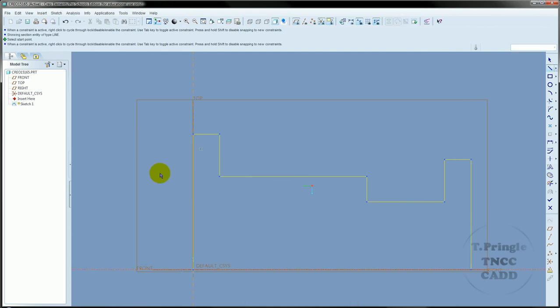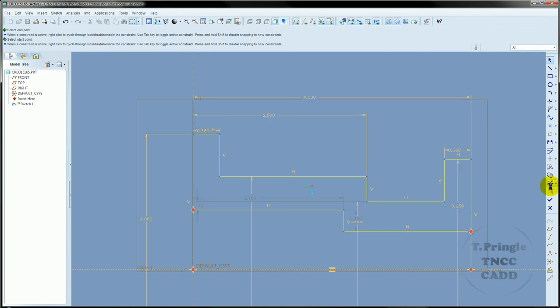What I'm going to do now is draw 2 lines, just come over this way, down, and then out to the end here. And now I'm going to delete segments, and I'm going to delete this segment and this segment. Now what you'll notice is I do have a shaded model to work with now, so when I go to extrude, I know this is going to work.